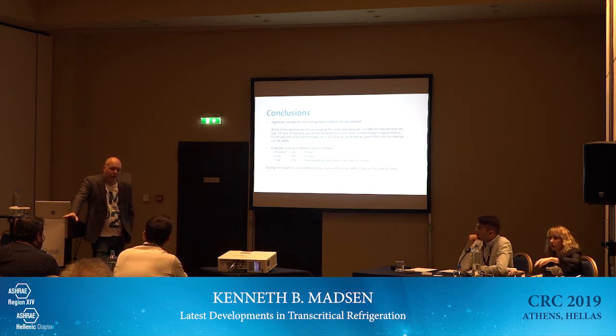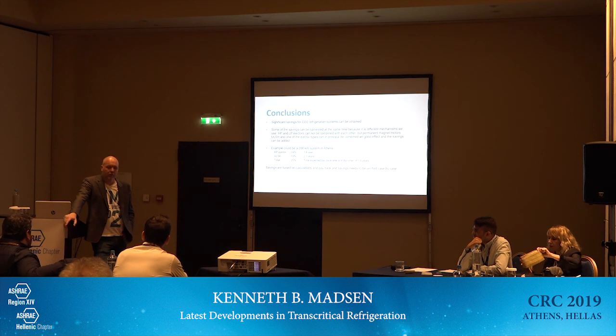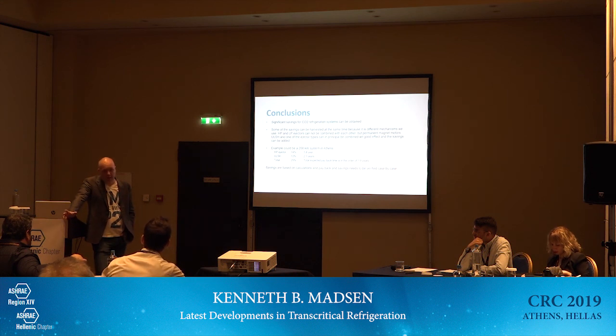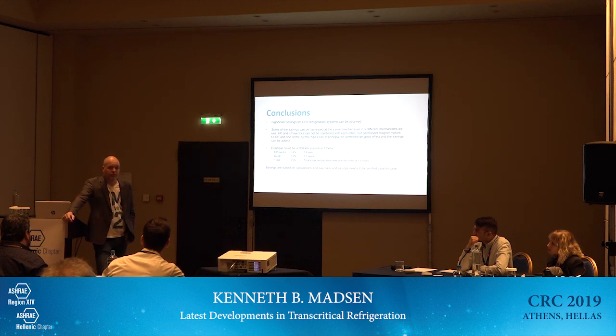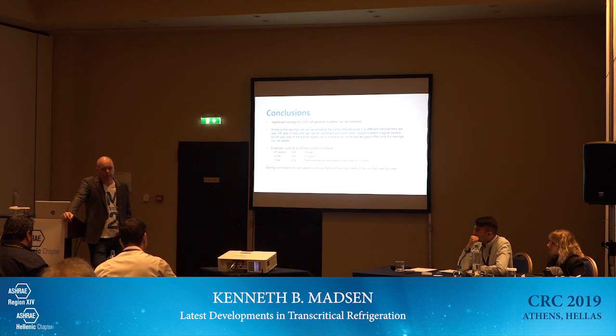And if the liquid level is too high, then we ask the compressor or the evaporators to stop flooding, to go back to high superheat. So that's the safety concept we have. And the controller is also made so that if you lose the bus communication, then after 15 minutes it will automatically return to high superheat. So there is some safety.